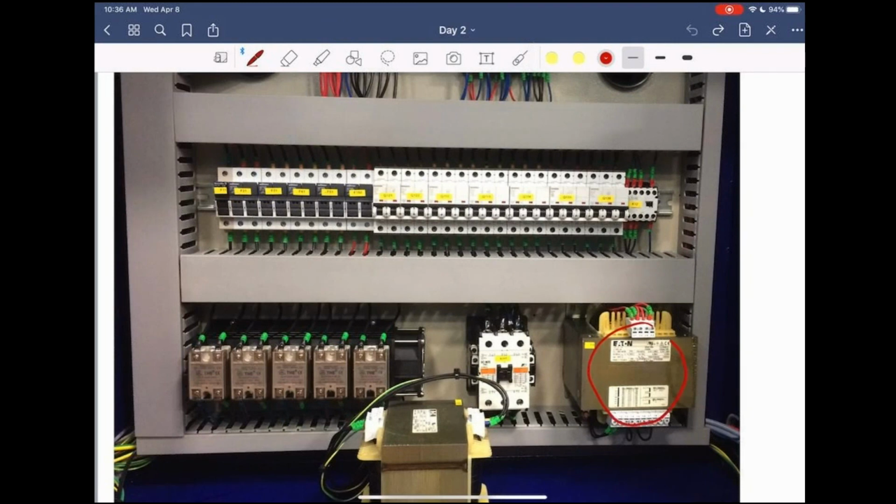That power supply is for your 110 volts going to the 24-volt power supply. So it's a transformer, I'm sorry. You have a transformer here. This transformer feeds the nozzle and all the fans on the machine. So keep in mind that the fans are not a 24-volt fan. The fans are 240 volts.